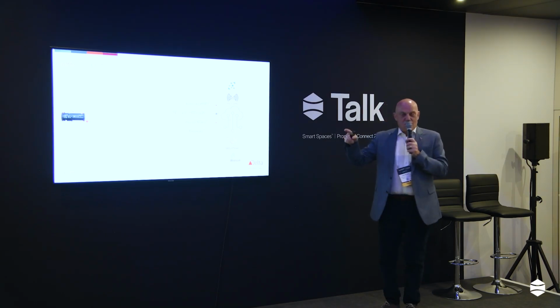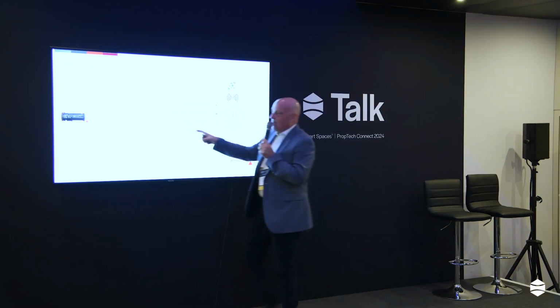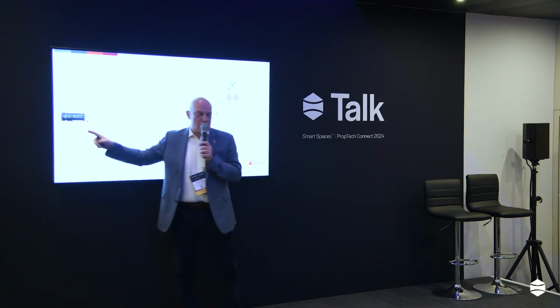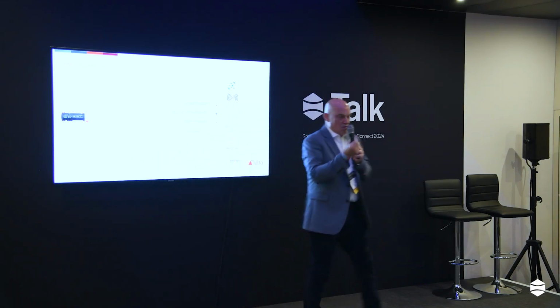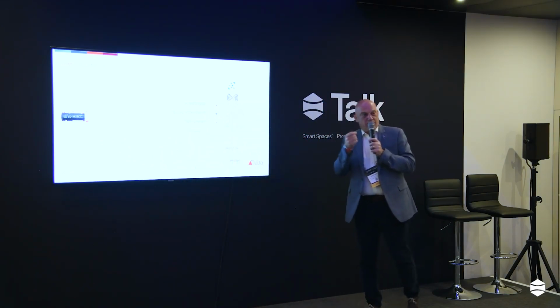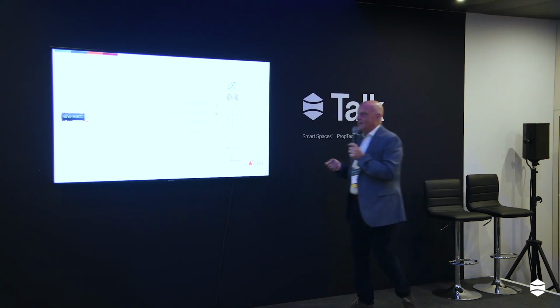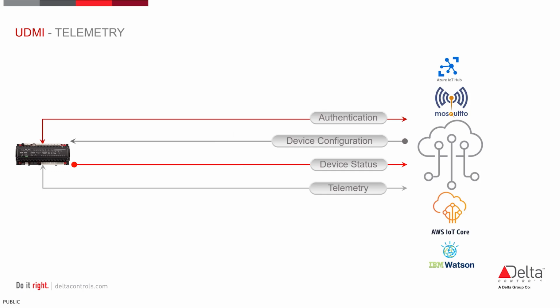Because the alternative of that is, if you think about a big building, there might be 1,000 of these in the building. So if you don't have some automatic system of doing it, then it means somebody has got to go to the building with a USB stick or something and update the firmware in 1,000 controllers, which is not scalable. So UDMI allows for that, and that's a really important piece of what UDMI does. That's why it's device management, not just a protocol.